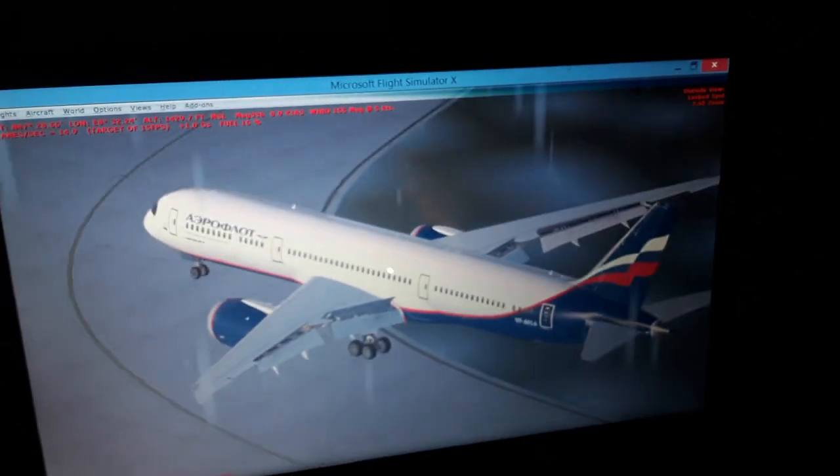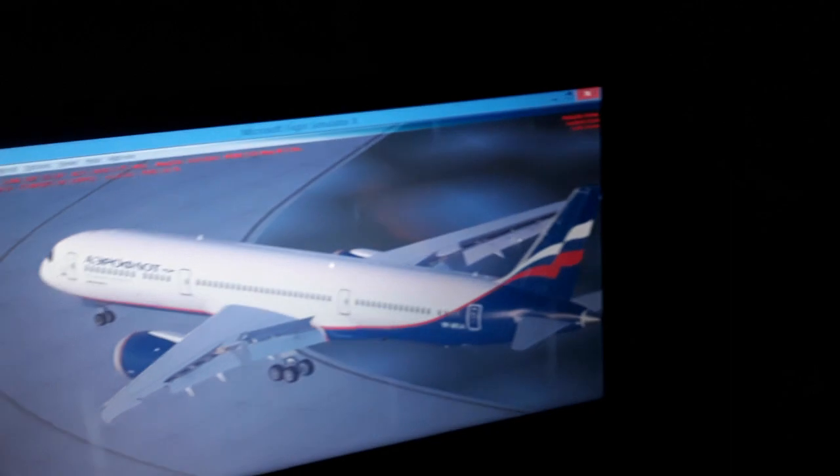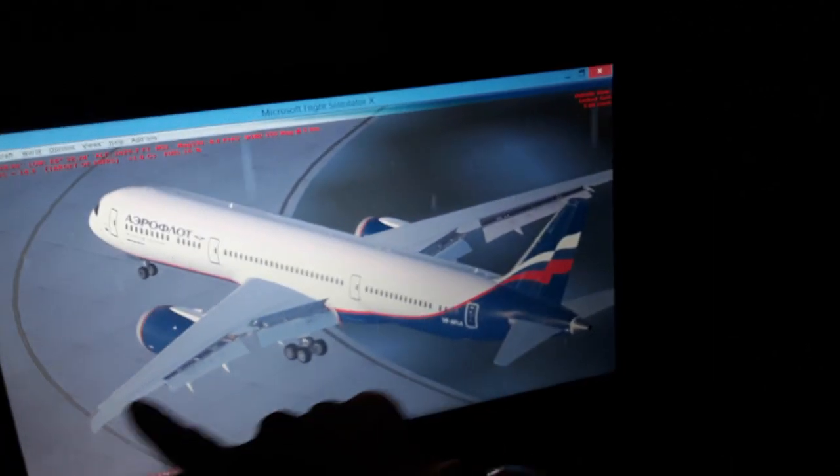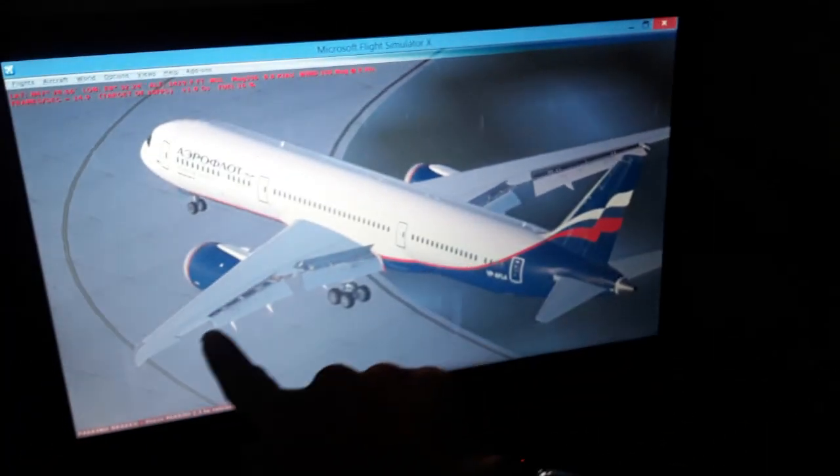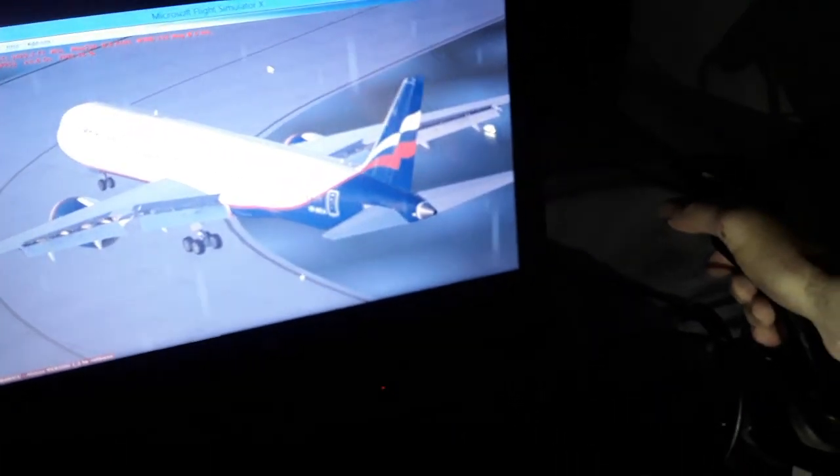So the center of gravity, this is the vertical axis, is the yawing axis of flight for making turns using the rudder pedals. So this is the yaw axis for making left and right turns. So we have also the lateral axis from wingtip to wingtip. It's the pitch axis. The pitch axis is the elevator axis for climb and descent, like this. For climbing the aircraft up or down in flight.